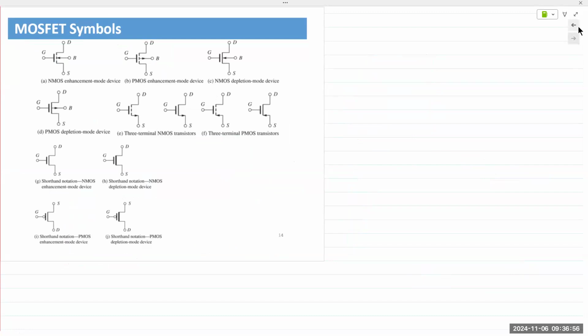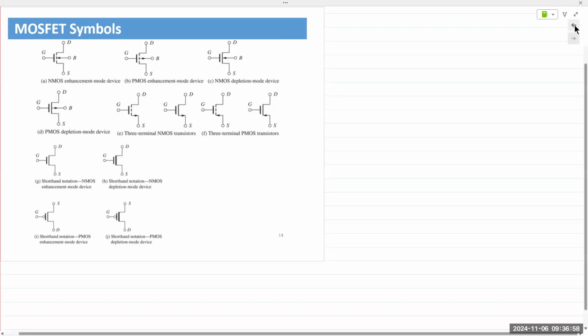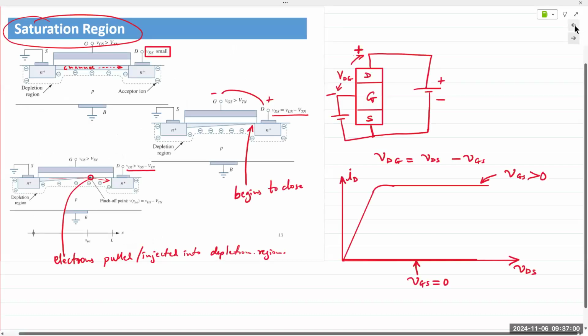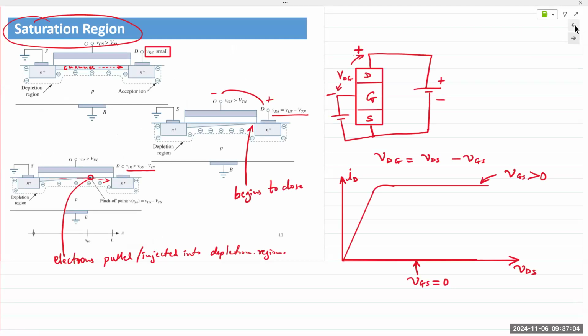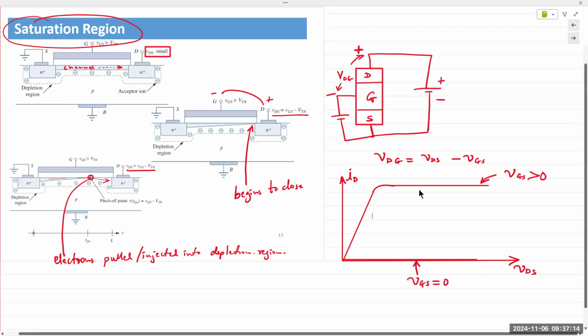Yes. Oh, I have a question on the previous slide, actually. I was doing some reading online, and it said during the saturation region that it acts almost like a current source. Is that true? It's just stuck at that current level, right? Yep. The question being asked is, like the JFET, does it act like a current source?